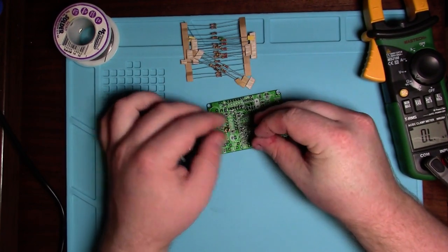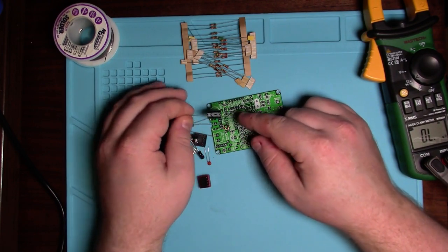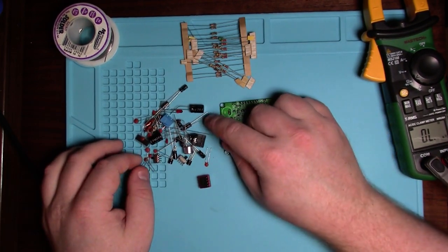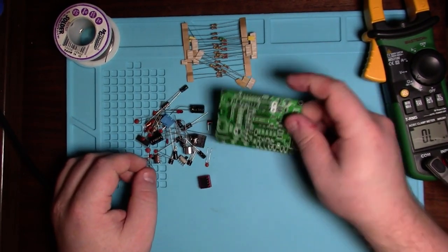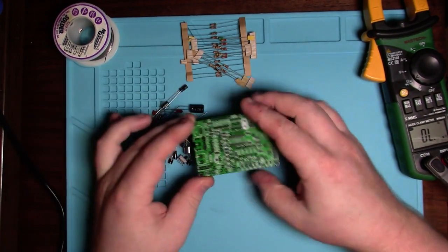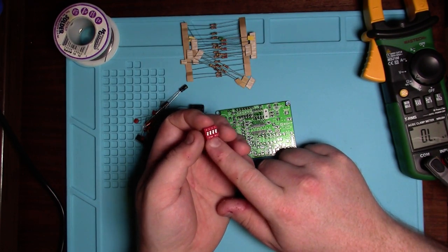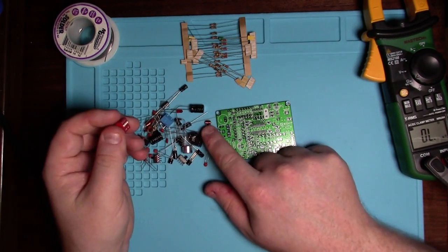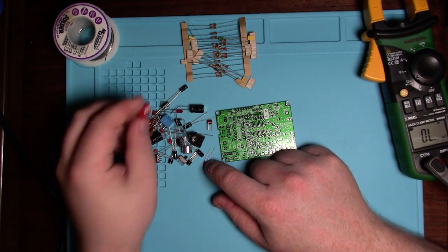But if we put an inductor and a capacitor together, we get an oscillator, because it's going to try to oscillate at a specific frequency. And that is actually how the tuning on this transmitter works. You'll see it. We have a set of switches here, and what it's doing is using these switches to switch in different inductors and different capacitors to tune the circuit. Pretty cool.